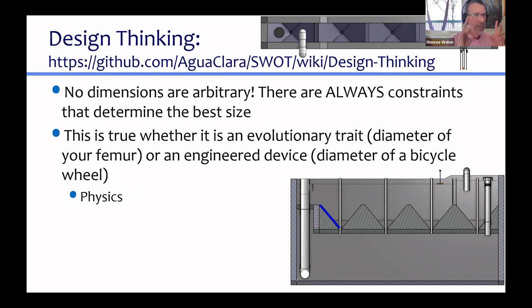Usually where there's scree close to a hiking spot, there'll be signs: don't hike on this, because the whole thing is just waiting for an avalanche, right? You don't hike on scree. Well, we're trying to create a system that's avalanche ready. It's steep enough so things will slide down. If I look at that, it looks like my angle is probably 50 degrees, which is also what we use in our sedimentation tank. It's steep enough that just about anything will slide down that steep of a slope.